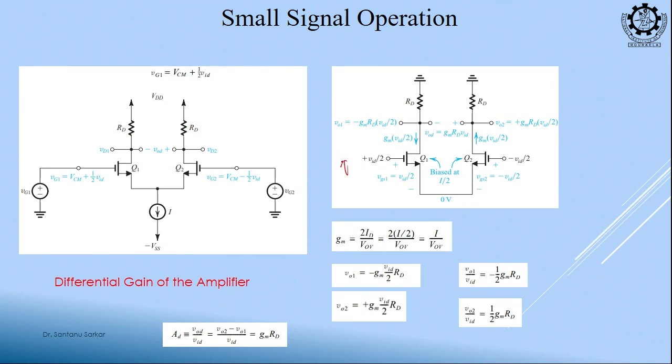If I change this voltage, what is changing? Actually current, right. This voltage was connected to VDD, so we will short it to ground, because it is AC analysis, all the DC sources should be removed, right. So, if del I is changing, what is del V? Del V is equal to del I into RT.